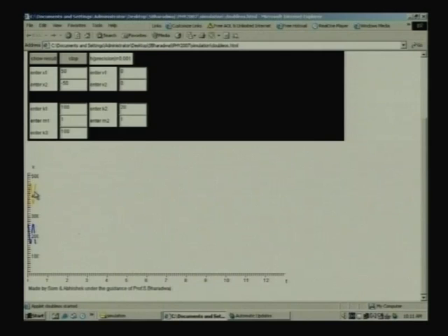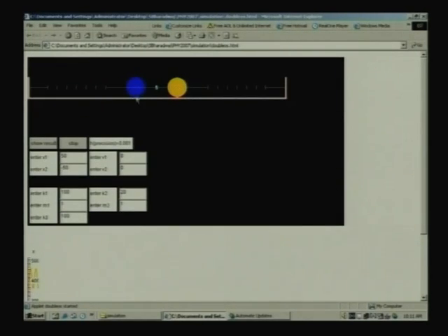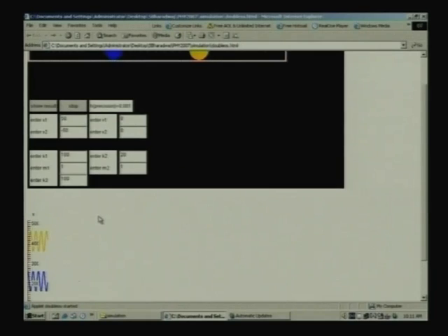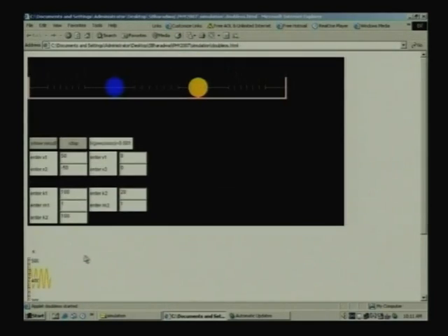And the pictures over here show you the motion of the blue mass and the yellow mass respectively. This shows you x as a function of time, and they are moving exactly out of phase. If you had looked at the same thing for the q0 mode, the center of mass mode, they would have been moving exactly in the same phase. So, what we have done is we have looked at 2 different kinds of disturbances, one which excites only the center of mass mode, the slow mode, and another which excites only the fast mode.